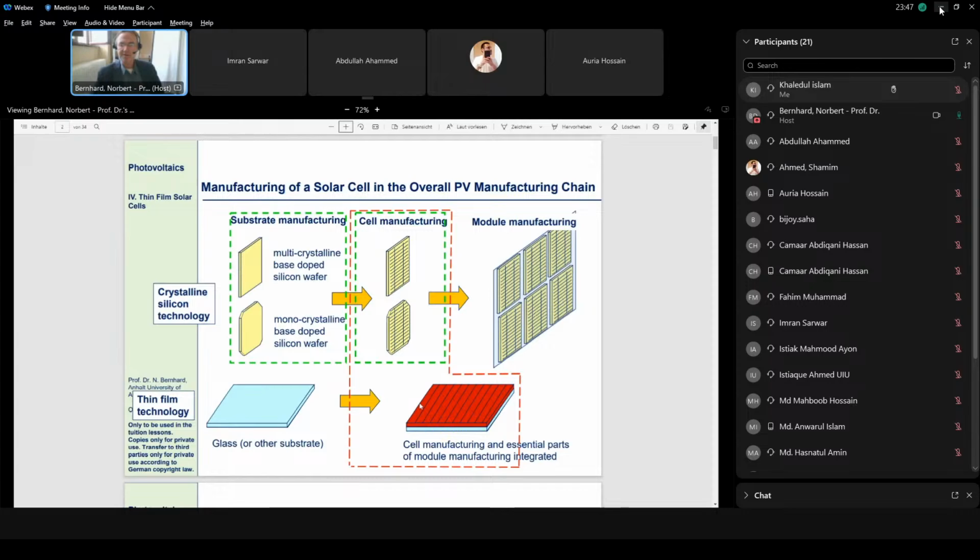Okay, this picture you have also seen already. This time I will only focus on the green colors, which are the thin film technologies. Here you see the open circles, which are amorphous silicon, and these are research efficiencies. The best amorphous silicon research efficiencies are roughly around 12% cell efficiency. And this is the reason why this material is no longer really competitive, because the efficiency is too poor, and there was not really any progress in this material in the last two decades or so.